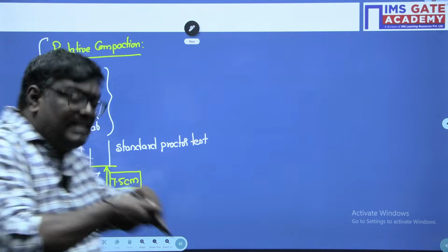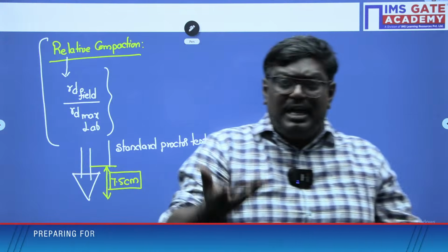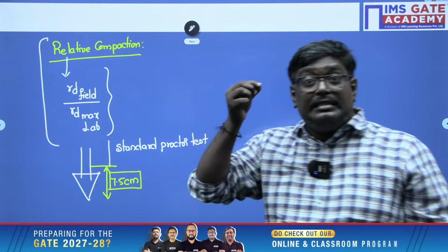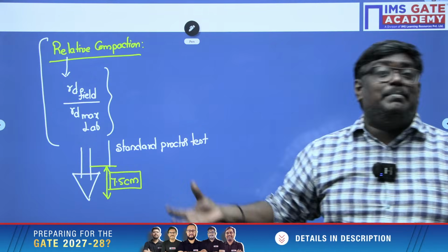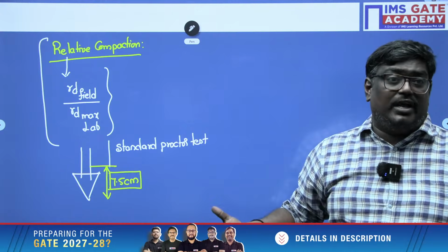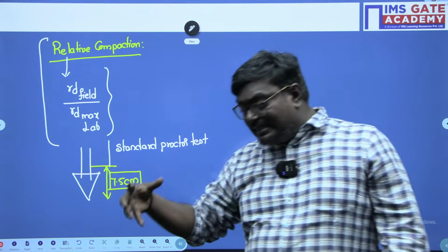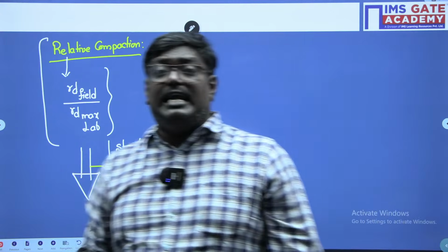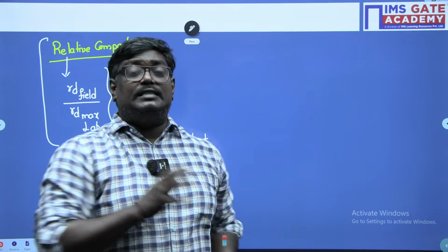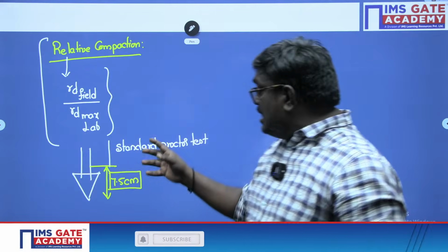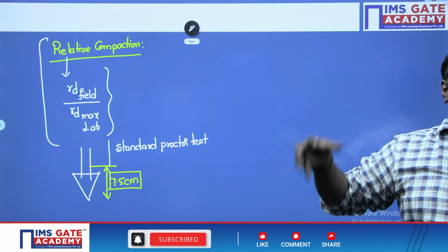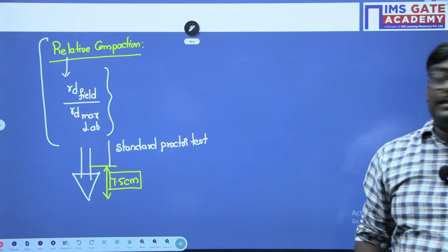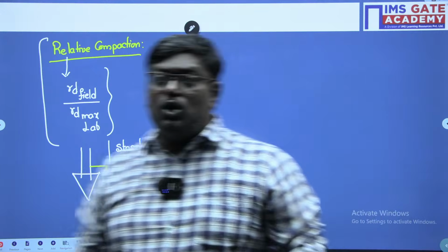If the needle is penetrating very easily, my dear student friends, that indicates it is a loose soil. If the needle is offering some resistance, then it is a hard soil. So this is a basic immediate test where you can get an idea on compaction. Here a Proctor needle is pushed into the soil and the resistance offered by it is measured. So this is all about relative compaction.